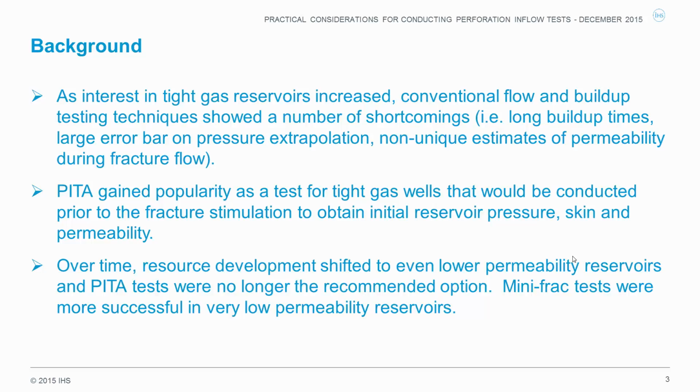So approximately 15 years ago, interest in tight gas reservoirs began to pick up, and conventional flow and buildup testing techniques began to show some shortcomings, such as impractically long buildup times due to very low permeability, and large error bar on pressure extrapolation, since the final buildup pressure at the end of the test would not be close to the average reservoir pressure.